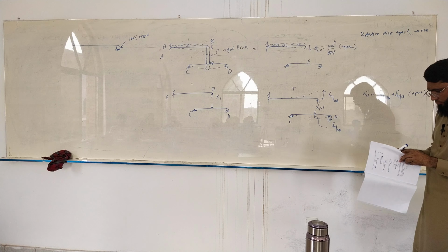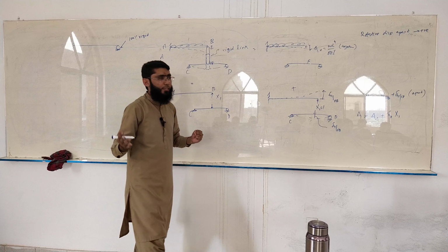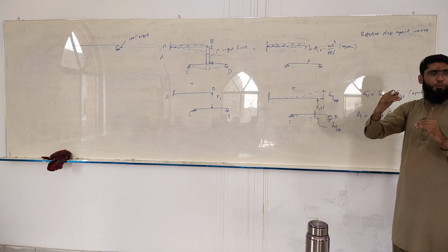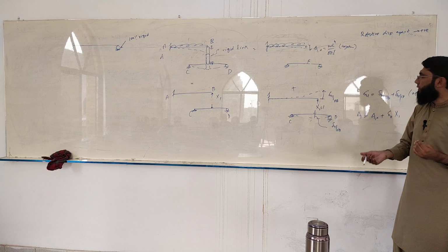In the given beam, this is important to understand: what is the relative displacement between E and F? It is 0. Even after the application of the load, they still remain the same distance apart. Although they both displace downward, the relative displacement remains the same, equal to 0.